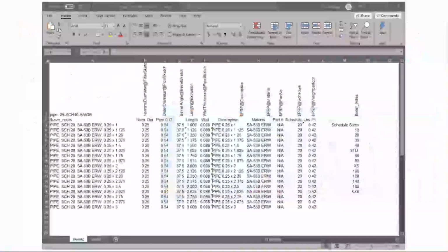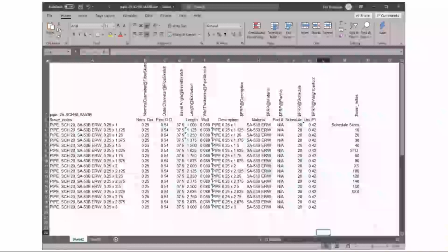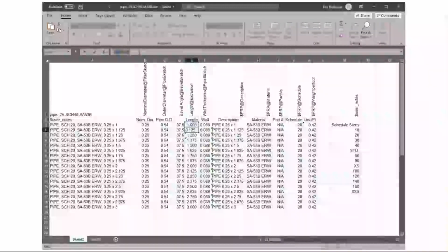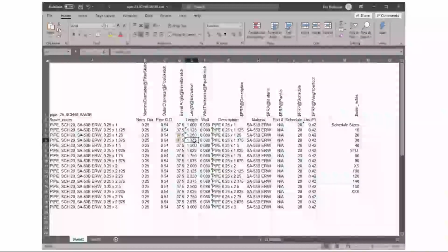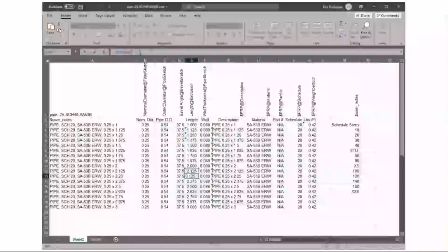I mean, you have the power of Excel at your fingertips, so you could really use anything that helps you out. So here's the Excel spreadsheet. This is a separate file that we'll read in. As we take a look at this, I'll highlight the length field here. That's the first keyed in value, 1 inch, and then a formula: E3 plus 0.125. Because it's Excel, you can copy and paste all that, and it auto increments the cell and just continues to take the next cell plus 1/8 of an inch. So really, really easy to generate all the lengths in this example.